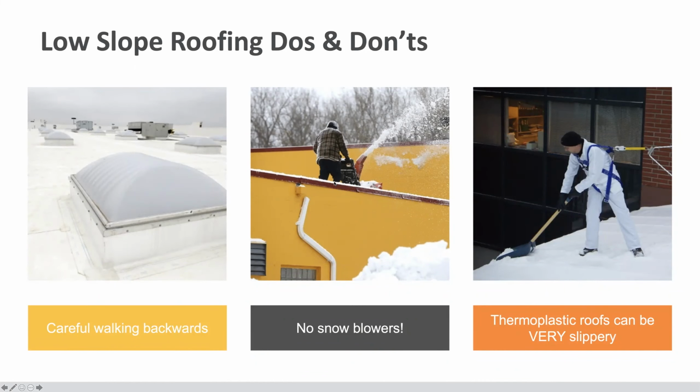Living up in northern Wisconsin, we see this more than I'd like to admit, but I highly recommend not bringing a snow blower up on your roof to remove the snow. You'll create more problems than you had before you brought it up there. And lastly, on the TPO and PVC roofs, all these thermoplastics are slipperier than water slides. If you're not tied off correctly or prepared for something like this, I just recommend having a professional in and not putting yourself in harm's way up there. They're very slippery.